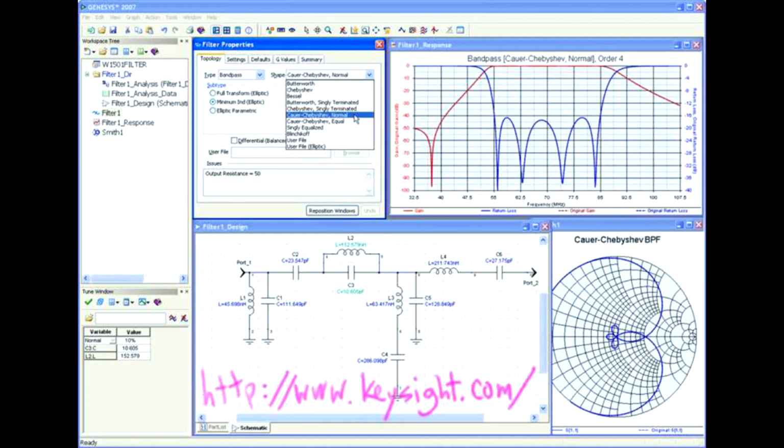It's a messy business, because simulating these things requires intimate knowledge of the properties of the components you've selected, not just the capacitance but much more than that, its frequency response, and also knowledge of the layout. Nuances of the layout can affect the performance of the filter in different ways.